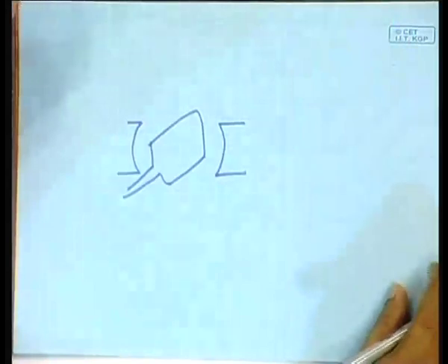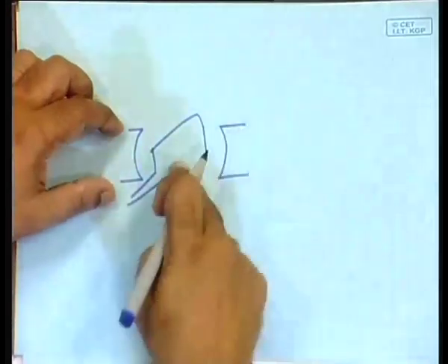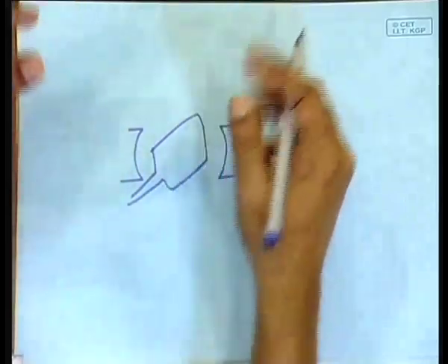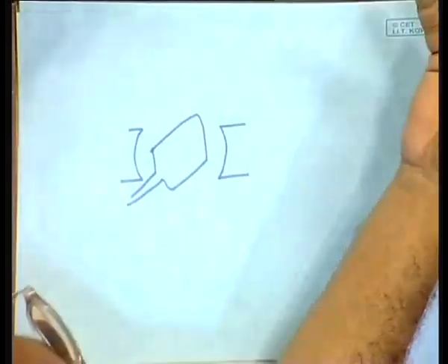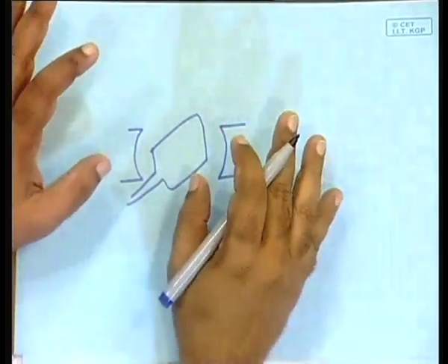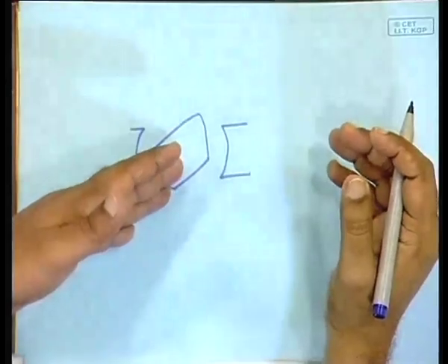and then it is worthwhile to tell you that the field is not really static and the armature rotating. It is the opposite, the armature static, the field rotating. Why? Because the armature has to carry the bulk power and the current. So, the conductors are thick, and so it is far more convenient to put that in the stator and put the field in the rotor.